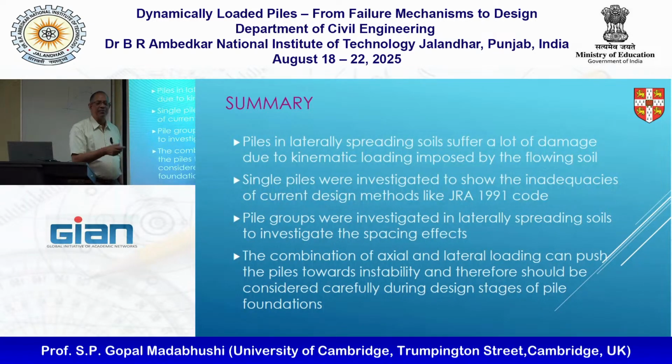I went and somebody gave me a copy of the new code, and I looked at the new provisions in the new code. They're exactly the same as that. They changed the date of publication. Closer piles will act as one large pile and rotate. Piles that are widely spaced will attract the flow of the soil. They almost act like single piles.